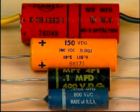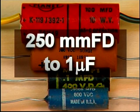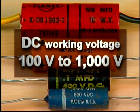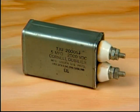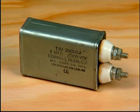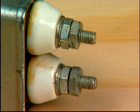Paper capacitors range in value from 250 picofarads to 1 microfarad with a DC working voltage range between 100 to 1000 volts. Paper capacitors used for high-voltage circuits are impregnated with oil and then sealed in oil-filled metal containers. This capacitor has threaded studs with nuts for terminals.